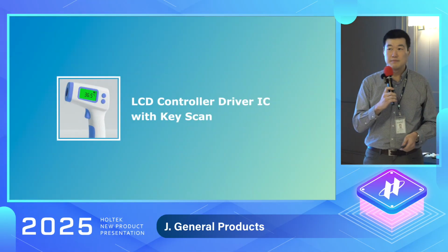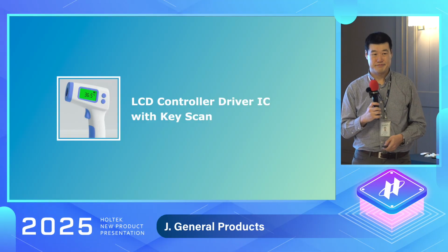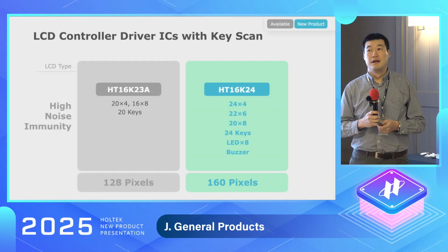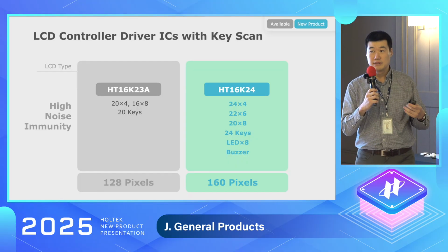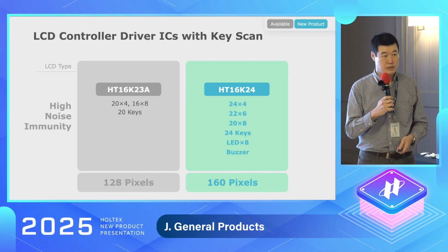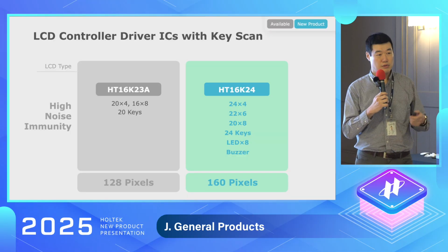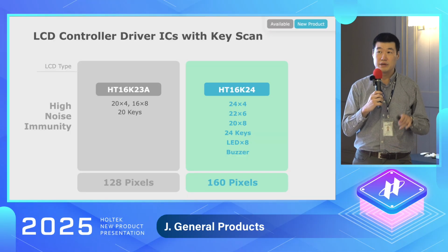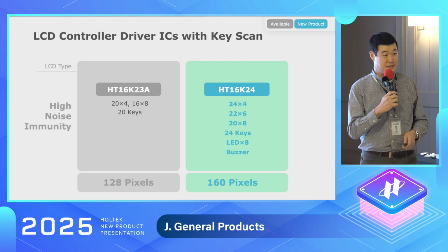So let's talk about our new product, LCD driver IC. This year we released our LCD driver IC. We put in up to 24 keys, and we support up to 8 pieces of LED driver. We also put in a booster driver, and we can support up to 160 pixel LCD.